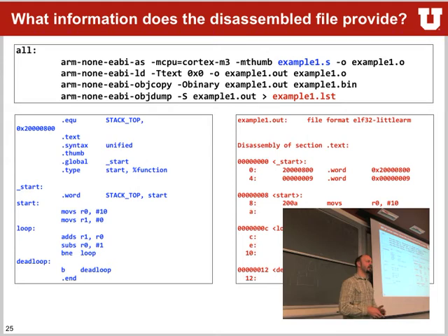It's actually telling the microcontroller that whatever is at this location is a thumb instruction, not an ARM instruction. So if this were 8 in here, it would mean that wherever you jump to is an ARM instruction. And if you ever try to do this on your Cortex-M3, you will get a hard fault, because the Cortex-M3 cannot execute ARM instructions. We will see when this is added, +1, or when it's not. Sometimes you don't have to do it because some of the jump functions do not switch your execution code, but others you have to add +1 to the memory location, or else you will get a hard fault. Sometimes very confusing to figure out what's going on.